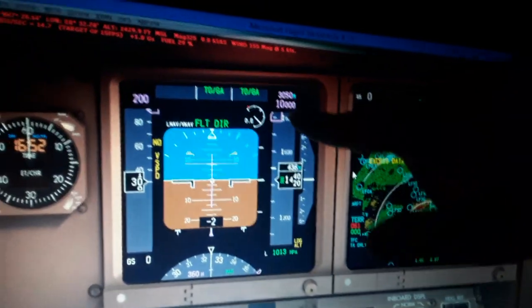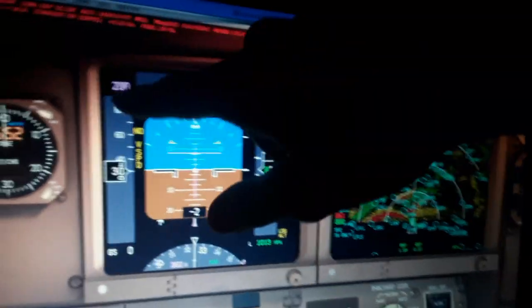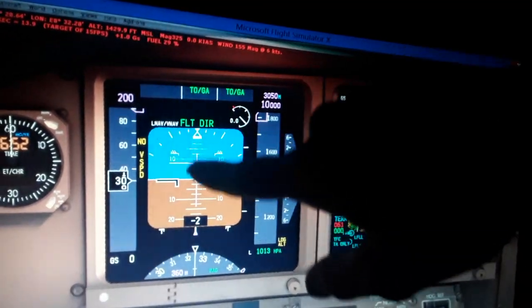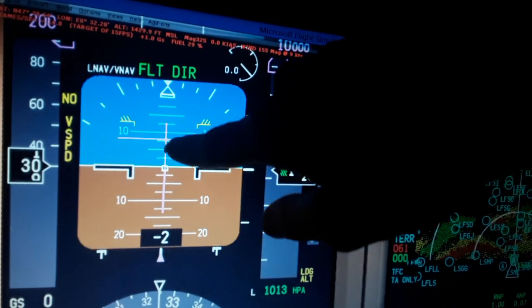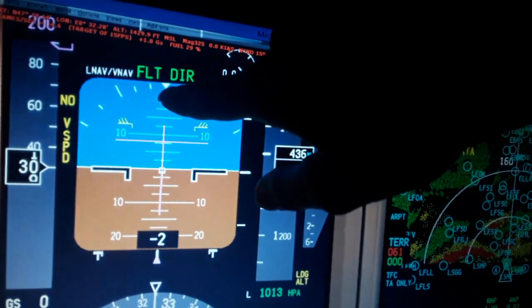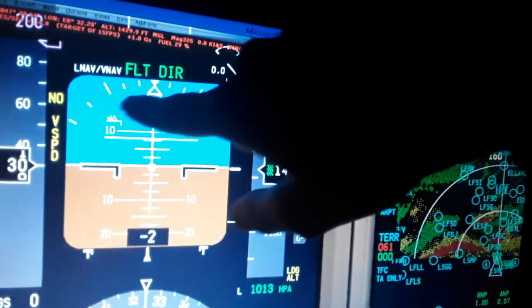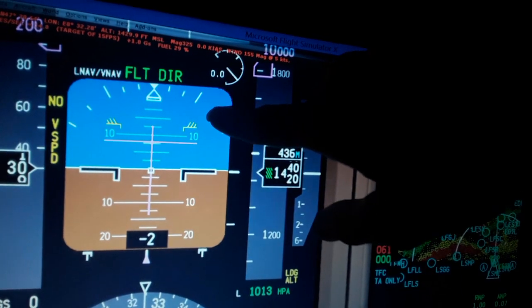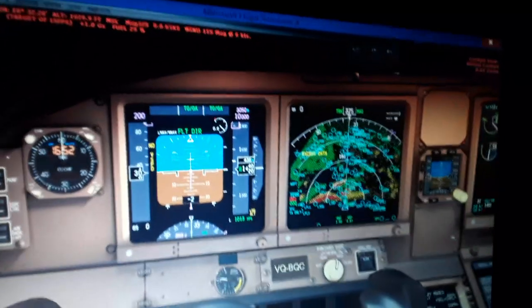So you have the altitude also in meters, the altitude selected, and this is the airspeed selected from the autopilot flight director system panel. The pitch ladder in degrees, you can see 2.5 degrees peak marks, 2.5, 5, 7.5, 10. It goes all the way up to 20 plus or minus, and the bank angle in degrees like 45, 33 or less.